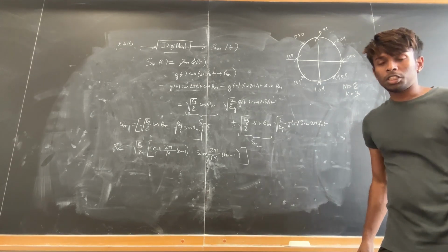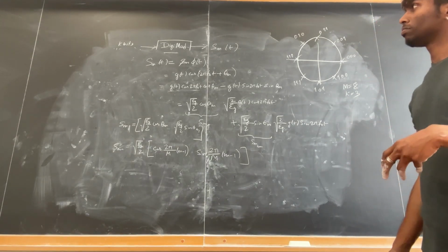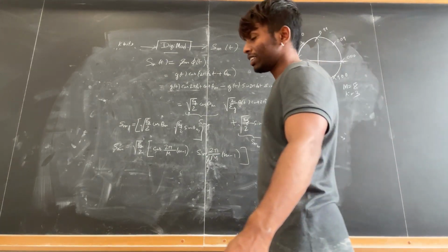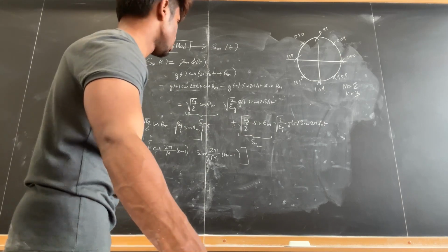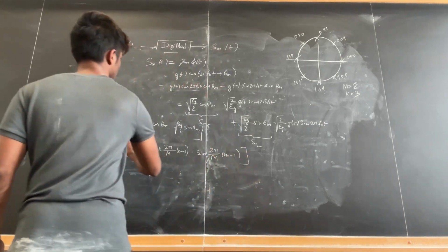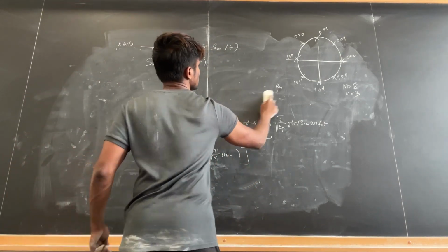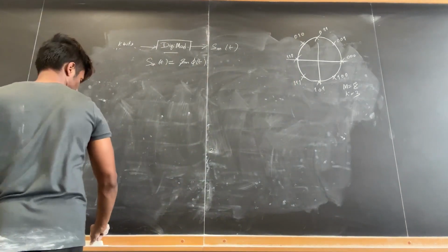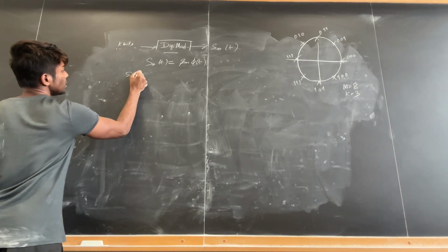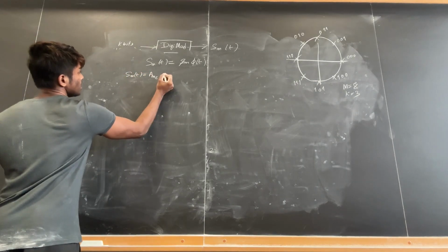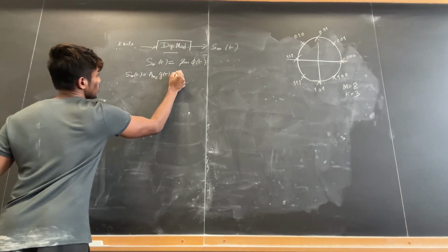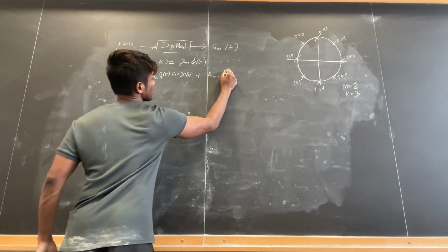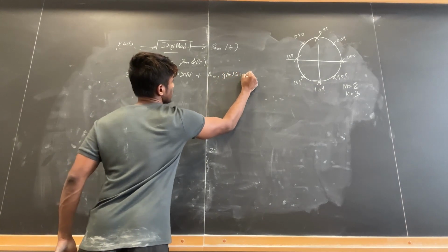Okay, cool. After the phase shift keying, the next method of digital modulation is quadrature amplitude modulation, that is QAM. Again, we can expand on the same idea. Snt is equal to Sn times phi t. But now we take a combination, that is Smt is equal to Amc gt cos 2 pi f naught t plus Ams gt sin 2 pi f naught t.